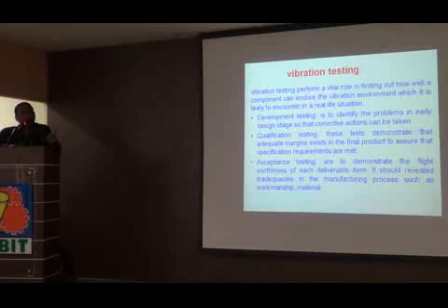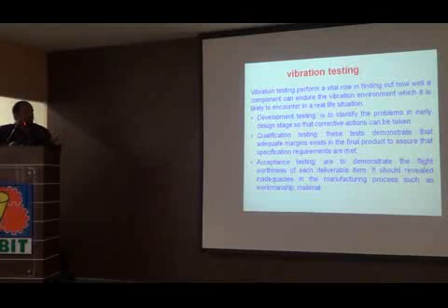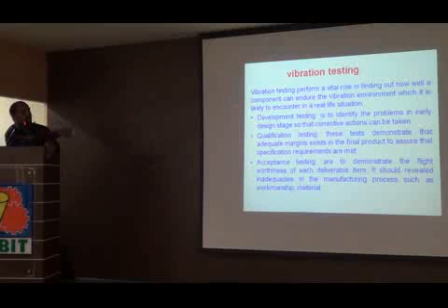Second, we need to check whether the electronic systems are functioning as per their intended specifications during these environments. So we have to simulate the correct environment and see the functionality of the electronic systems. These are the two major things that we check during vibration. There can be different types of testing methodologies. For example, during development testing we do one kind of input; qualification, which is a high level testing, another type.